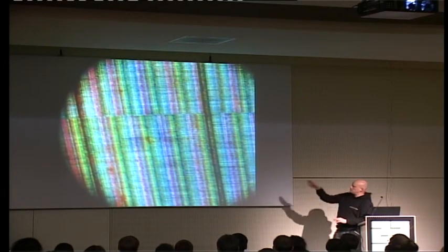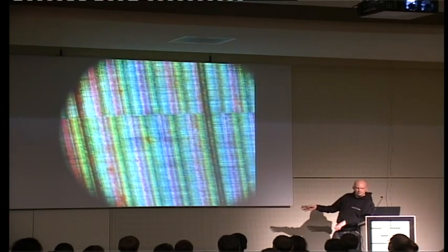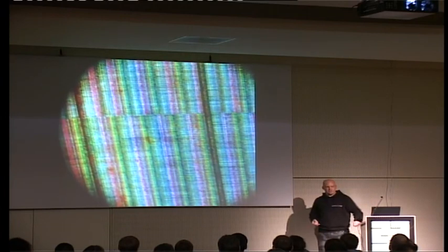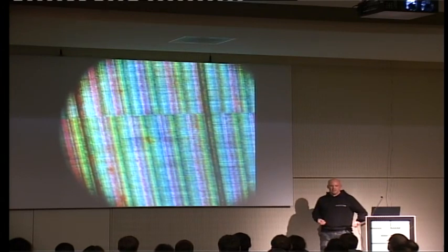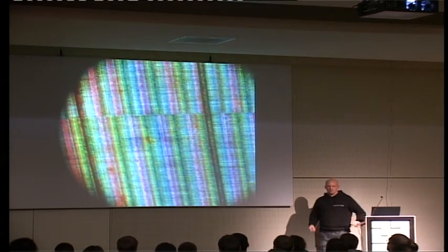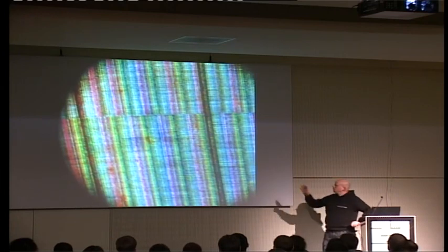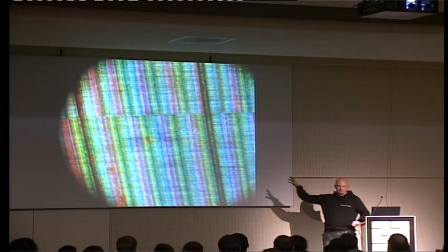For instance, the dark lines you see here are servo bursts, because the servo bursts, well, maybe I have to explain what they are. The servo bursts are marks on the hard drive to tell the heads where they are. They are usually stronger than the data transitions, the transitions that are writing data sectors. So you can actually distinguish data from servo.